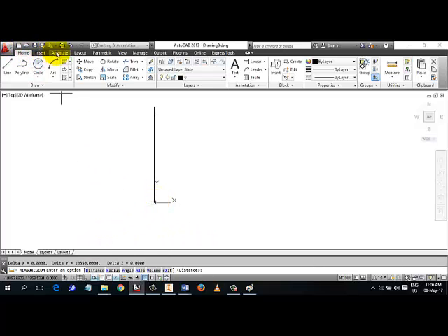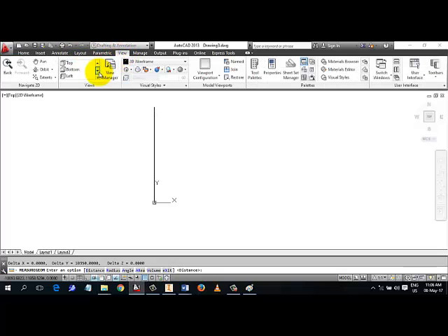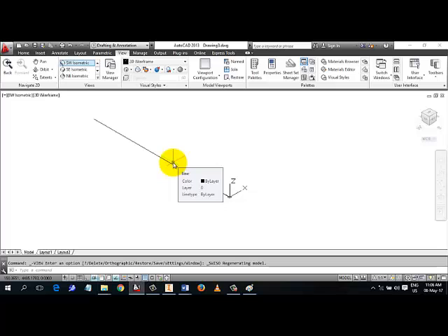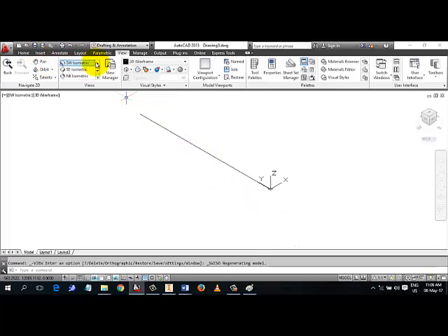Then, if you want to change to 3D, I've done that several times. Go to View, under Views panel here, you pick any of the isometric, then you're going to have what we call XYZ. You see that? This is 3D. And you see my line that was standing first is now lying horizontally. So my XY plane is horizontal now. If you watch my video on 3D lecture, you understand more of this. You're going to enjoy it. I promise. Anyway, let's change our orientation back to top.